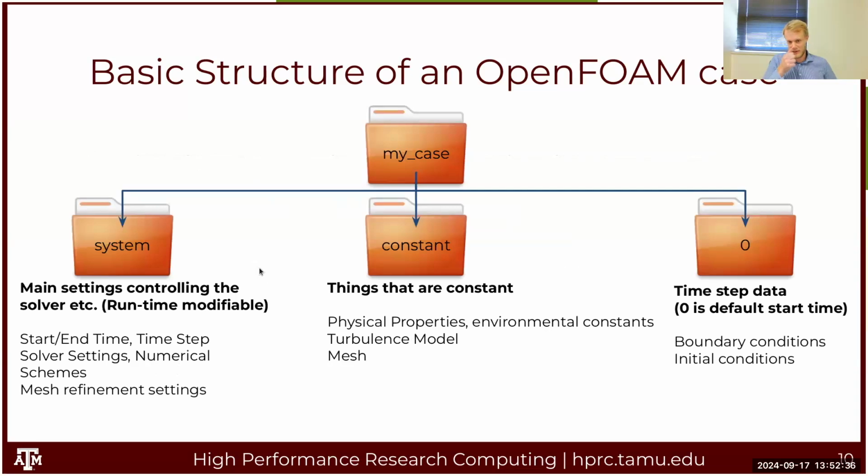So what's inside that folder? In this case, it's called my case, but again, it could be called airfoil or whatever it is you're simulating. Inside every OpenFOAM case folder are 3 main subfolders that are almost always present. There's one called system, which contains files that control the simulation, the solver, etc. These are usually runtime modifiable.